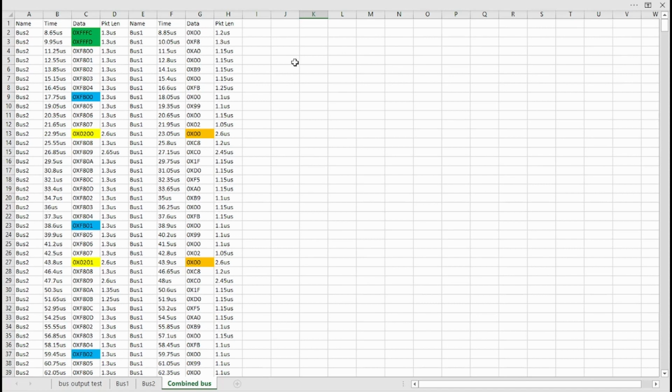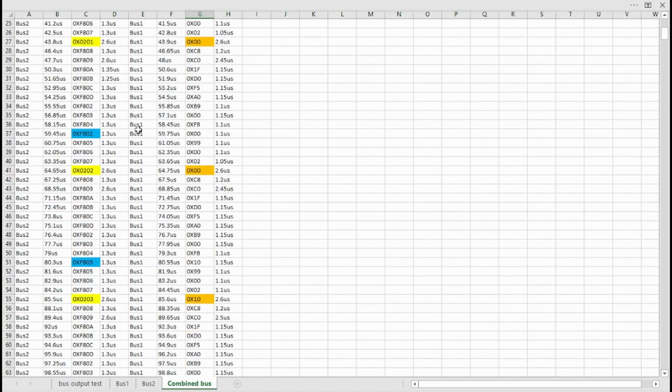So just a quick run through, we've seen the first part before, so FFFC, FFFD, we're getting our F800 and that jumps us to F800. I've highlighted in blue where we're looking up in the screen area of the ROM. So we start with FB00 and we're reading 0 and then we're writing it to the 0200 area, and I've highlighted that in yellow and orange. So all looks as we'd expect.